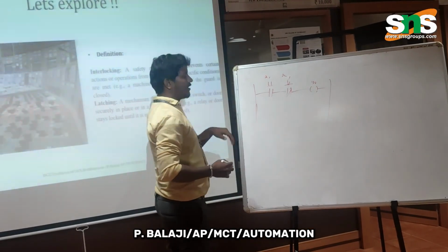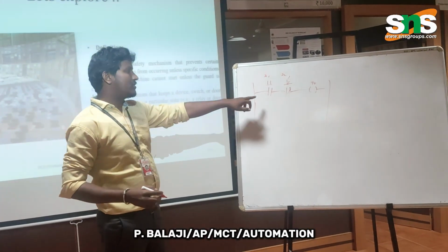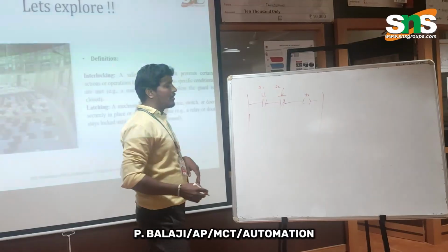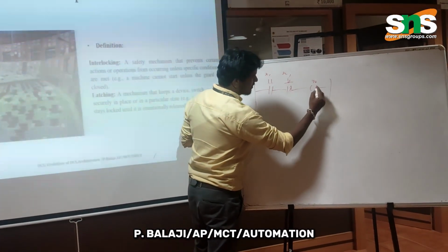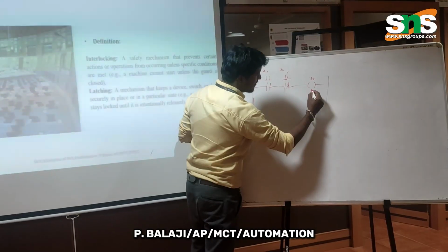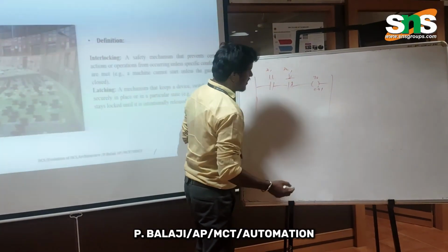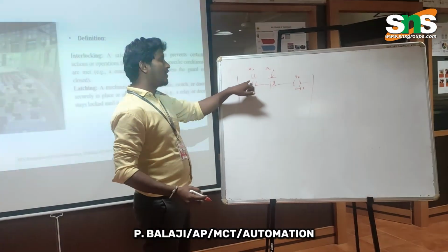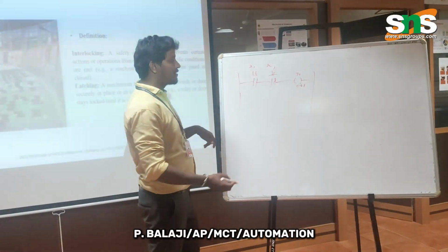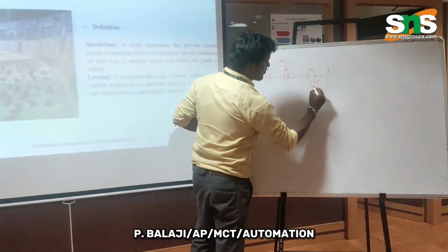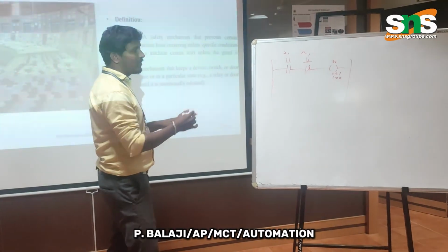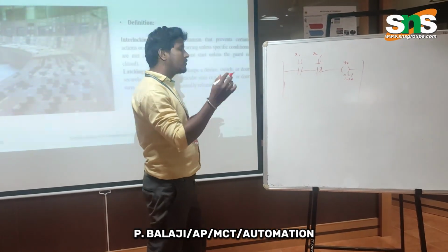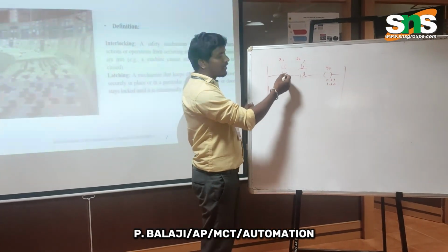So when I press start, the normally open coil closes and the circuit gets energized, so this lamp will be energized. It may be 0 to 1. At the time when you release the switch, it changes from 1 to 0. But it has to stay on even when you release the switch that opens the coil.